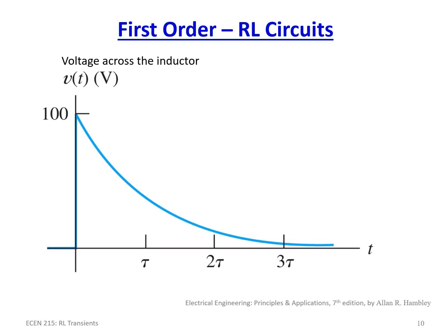And then, of course, the voltage across the inductor as time goes on is initially equal to Vs. So the switch trips, and at that very instant the voltage across the inductor is equal to the voltage on the power supply. Because the inductor immediately tries to resist the change of the current going through it. In other words, it wanted 0 amps going through it. That's what it had initially. And now you're going to put current through it. I don't want that as an inductor, so I'm going to apply an equal and opposite force, but it will eventually decay over time. And this is exponential, and it's going to be V of t. It's going to go from 100 volts, and it eventually will decay to 0.